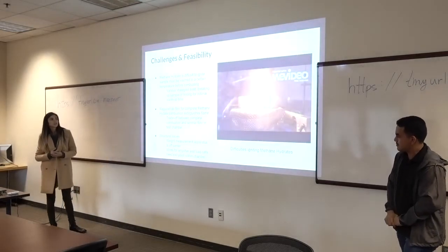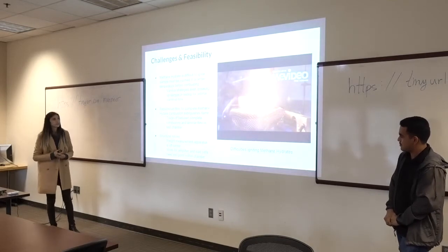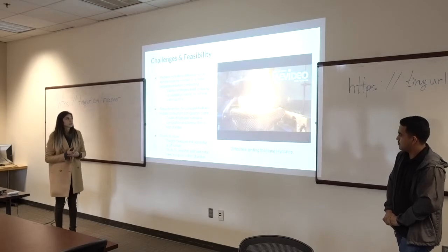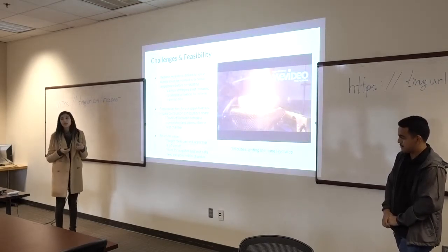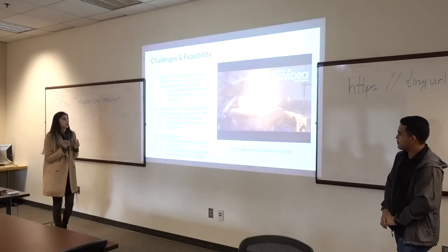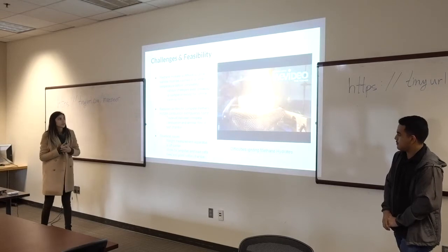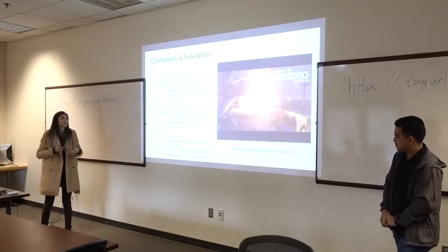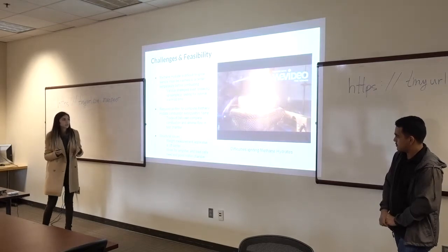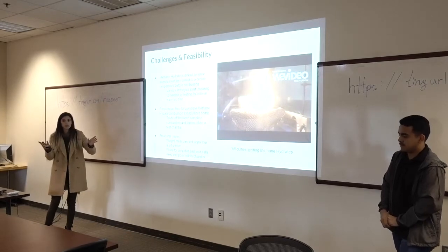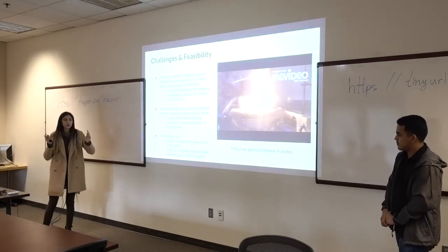So to conclude, some of the challenges that I previously mentioned through the video is the fact that methane hydrate is difficult to ignite, so we have to figure out strategies like breaking up the sample and allowing for warming time, preheating basically. Another issue is the fact that the airflow is too fast, so it extinguishes the flame of the methane hydrate. So there's a trade-off between complete combustion and laminar flow. That's another issue that we have to address.